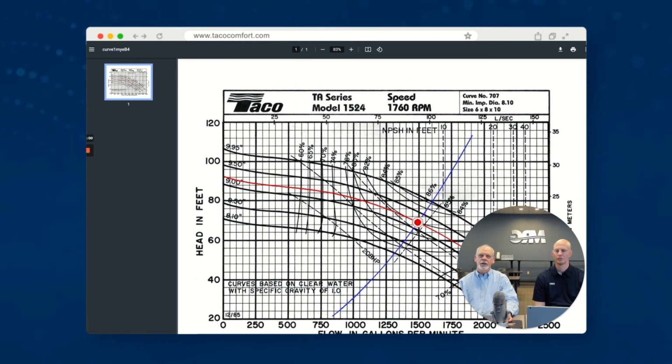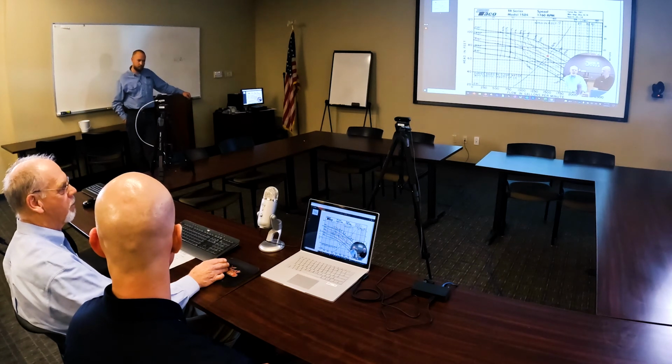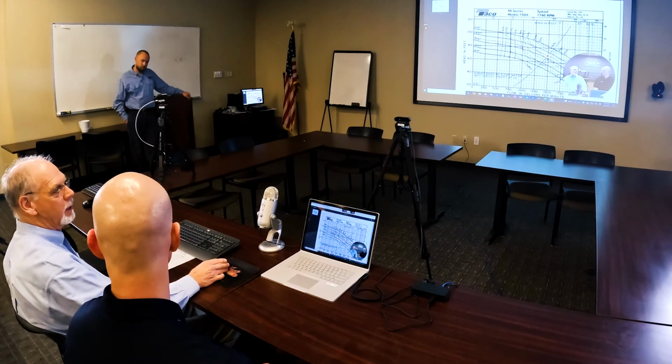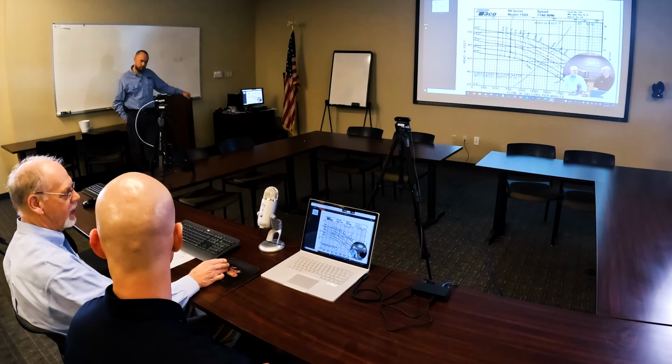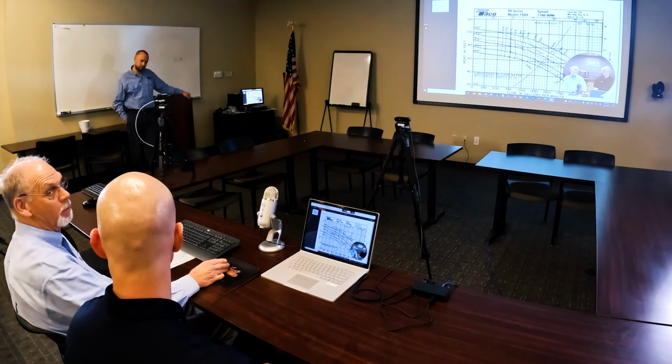And we can provide reductions through our suction diffusers. And also, we can use a smaller triple duty valve on the discharge sometimes, depending on our pipe size and the pressure drop through our triple duty valve, because it has to have a certain pressure drop to operate properly.